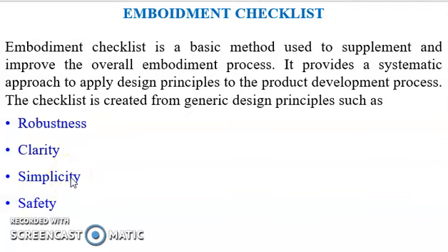Simplicity refers to minimization of information content within a product design. Component shapes must be simplified as possible for ease in the manufacturing and cycle time. Number of the components should be reduced to as minimum as possible, provided that the product maintains its satisfactory performance level. Safety. This design principle minimizes the risk created by the use of the product.